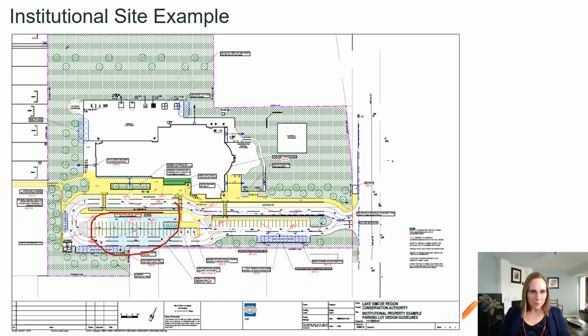It says that the roof leaders are discharging to pervious surfaces, and I can't see where those are, but something around here. It's discharging over to the grass here. They have elevated walkways, which again will provide drainage and prevent refreezing. And then rather than having curbs or landscaping features, they use painted end markers to ensure a clear path for the snowplows to operate. They have a number of snow storage areas, and these are all located away from high traffic areas, and also drain a short distance to a catch basin. And they have signs showing their location.